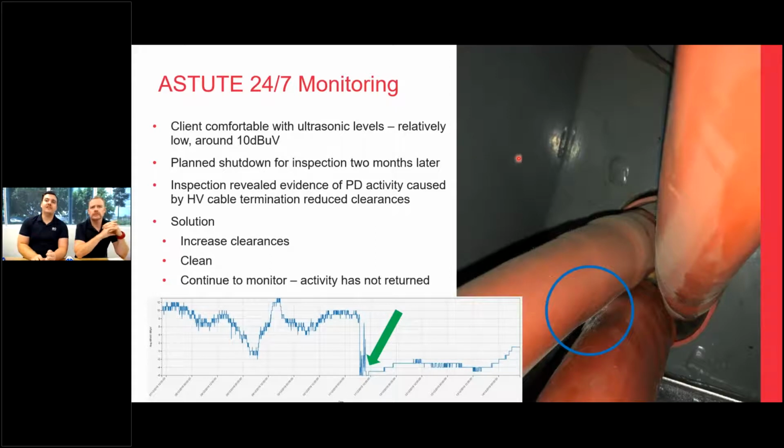And what you can see here is that these 2 phases were just a little bit too close and encroaching on each other's clearances. Therefore, you can see that build up due to the electrical interaction, and you can actually see a bit of dark burning starting to occur where the 2 phases were interacting with one another. So when they did this, they opened it up.